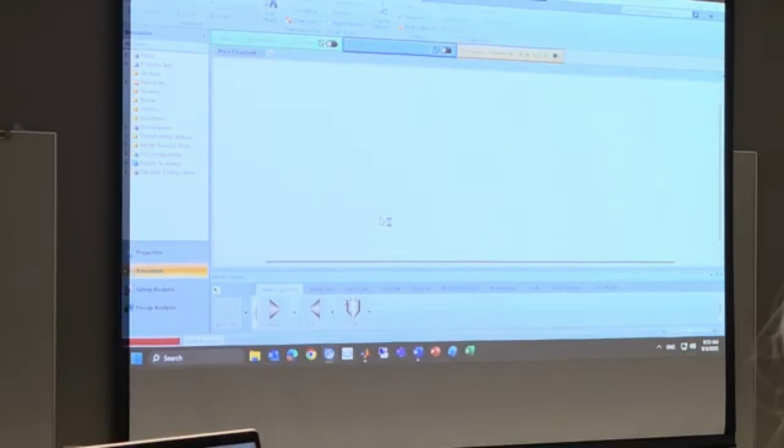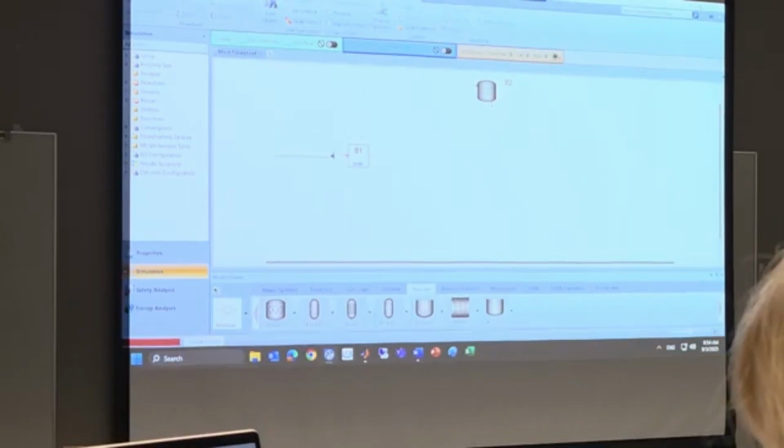If you look at the bottom, the model palette, we are working on reactors today. If you click the reactors tab, as you can see, we have 7 different reactors, very similar, but we will look at 5 different reactors today. Since we are simulating 5 different reactors, I may use a duplicate to facilitate our input stream. I can choose the RStoic reactor first, the stoichiometric based reactor. So let's connect our input stream.